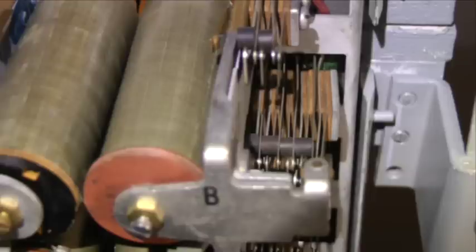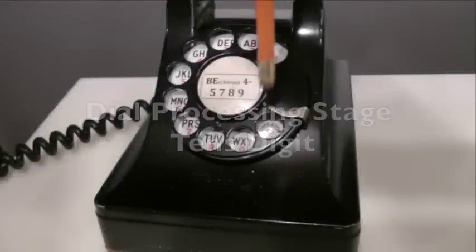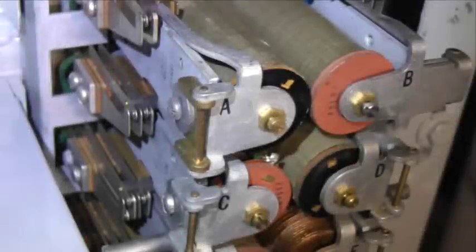It provides the holding ground to the incoming sleeve lead and also provides operating and holding grounds for various other relays in the connector. The caller dials the tens digit of the station number, which is a 0. During the dial's wind-up, the loop remains closed and the A and B relays remain operated.